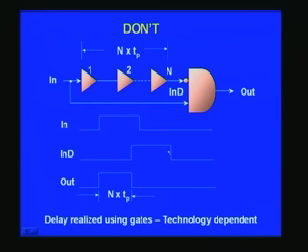So this is the delay that you have. This delay is governed by the total number of buffers that you have, and that total delay appears at the output also. So if you combine these two in this fashion, noting the bubble here, then our outcome is a single pulse, the duration of which is governed by this n times Tp. This is the traditional way, but this is unfortunately dependent upon the technology.